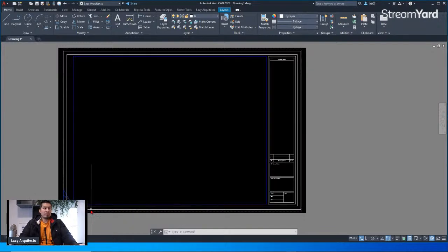This is known as paper space because this simulates a digital paper environment, all right, where you're gonna print your drawings, your floor plan in this case, your building exterior elevations, and so on. And paper space is also called layout. So many people know this environment as layout or paper space. And again, you're gonna print your drawings here using how? Well, right now, let me show you.